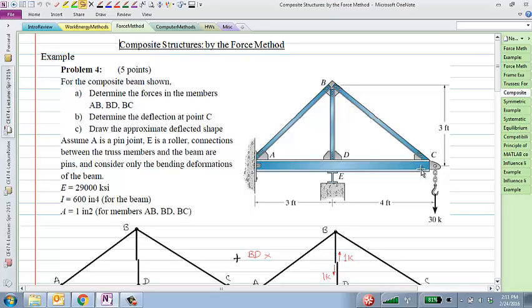What do the truss members do? They just deflect along with it, right? They don't really carry any load because they just reconfigure, they change the angle between themselves. So even that structure is determinate because those two members would be just zero forces.